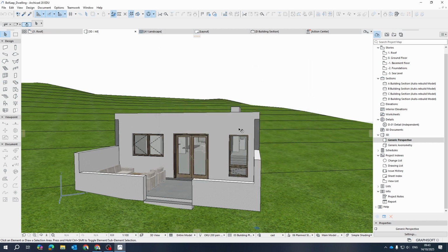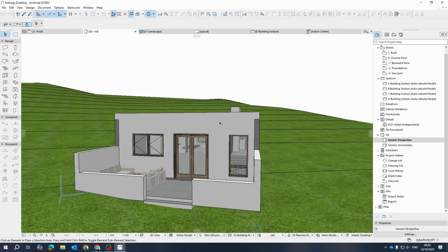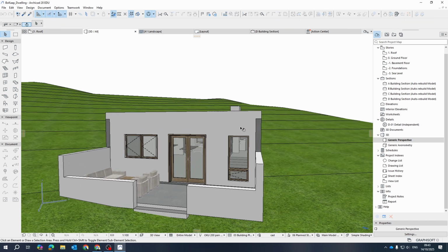Okay, so basically the levels drive everything in your projects. All of these elements that we use in Archicad, like the walls, you'll see that they're always referencing a level. So they always need a level. They link to levels. You can go and specify not linked, and then you can give them a height. Just as you change these things, this dialog box will change. So that's very important. Your levels will drive your floor slabs, your walls, your roofs. So the most important thing to do is get your levels set up.